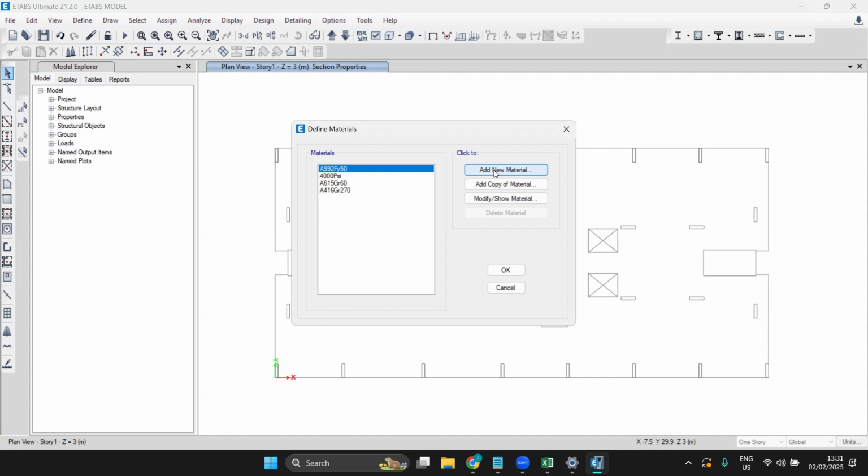What people used to do as a mistake, when trying to import, is keeping the basement at zero. It does not read it. Wherever you keep it, it will import the same basement in ETABS. You kept it away from zero. So don't change it. Imagine my typical floor is like this, and the next floor is like this, next floor is like this. But still I will not change the origin. I will just keep the same dimension.